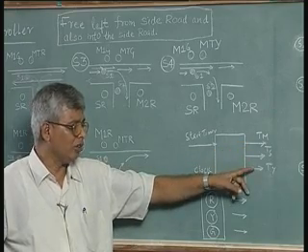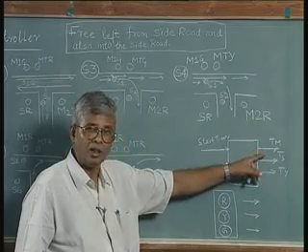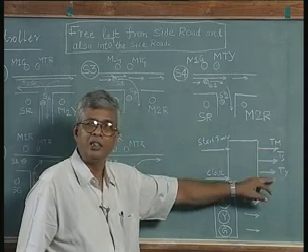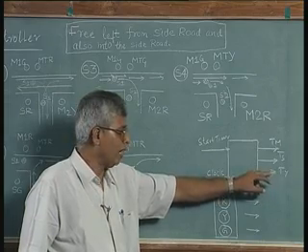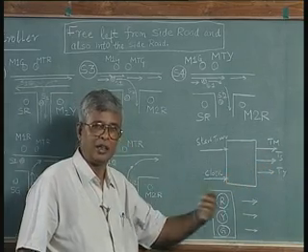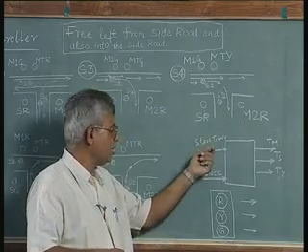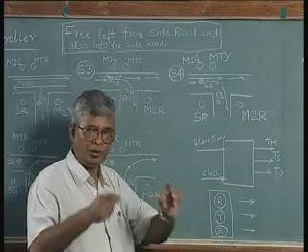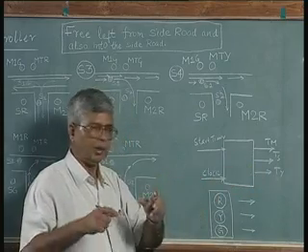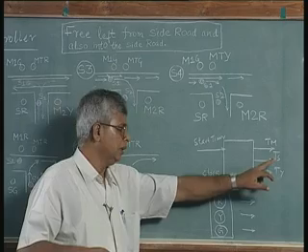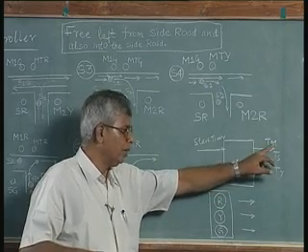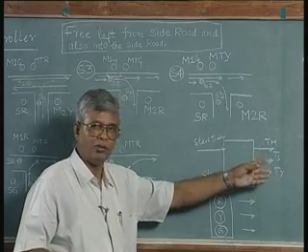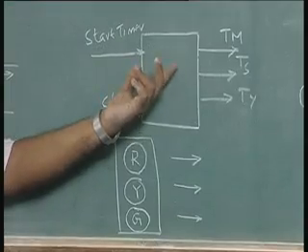These are exclusive events, these are not overlapping events. So, there is no overlap between any of these intervals. As long as there is no overlap between any of these intervals, I can have the same counter which can repeatedly reset and start. Every time I start the timer, it will start from 0, and after a particular time has elapsed it will become yellow, after a particular time has elapsed it becomes TS. There is a side road light green duration, main road green duration, yellow duration, and these are, as I said, mutually exclusive. So, there is no problem having the same timer do all of these jobs.